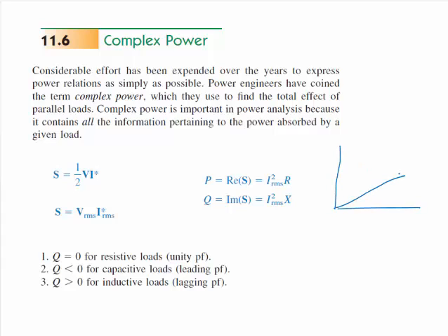I have a complex power right here, which is called your apparent power. If I just take the real power part of that, the real part is your average power, or the part that's real and dissipated by the load. Average power is now given this term P. And Q, or the quadrature, meaning it's in one quad of 360 degrees, or it's orthogonal. Quadrature usually means orthogonal, is your reactive power.